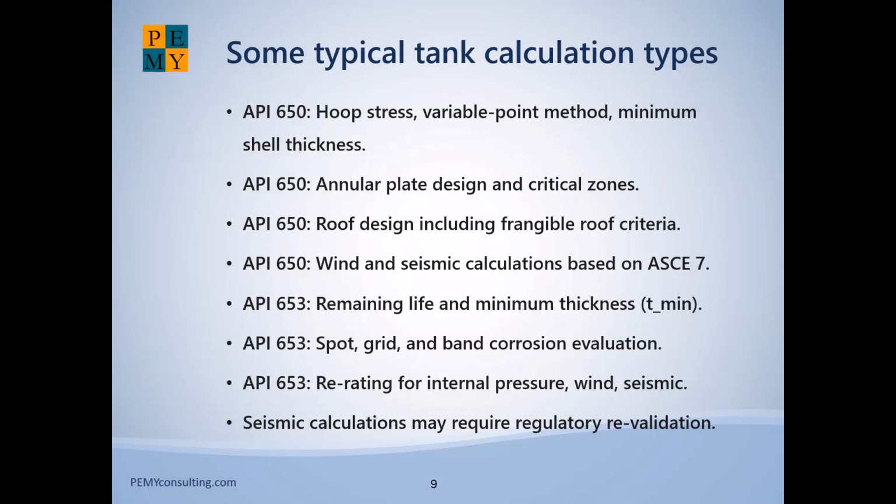For many small tanks, the required thickness for hoop stress can be substantially less than the minimum thicknesses specified by API 650. These minimum thicknesses are not needed to keep the stresses in check, but rather for things like constructability, fabrication tolerances, welding, handling, and long-term durability.